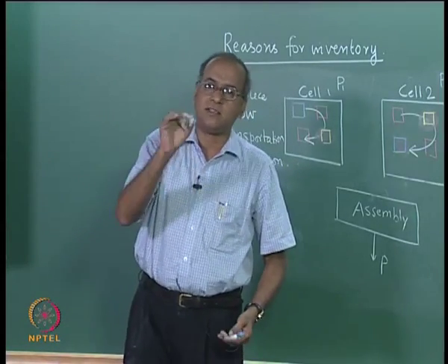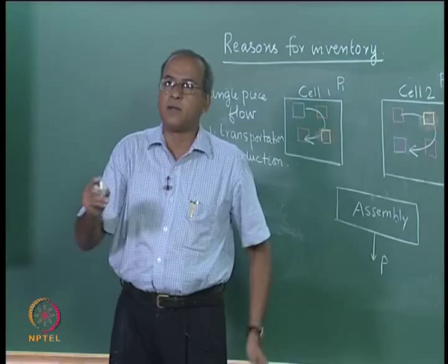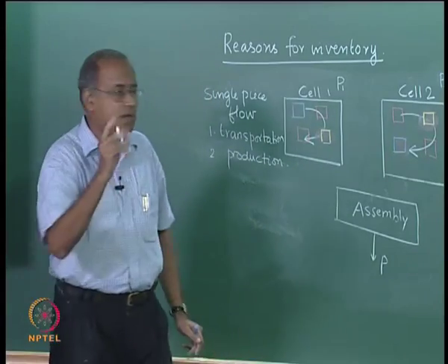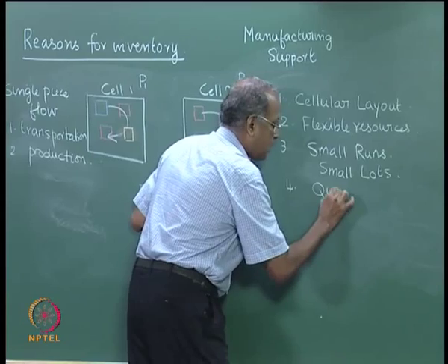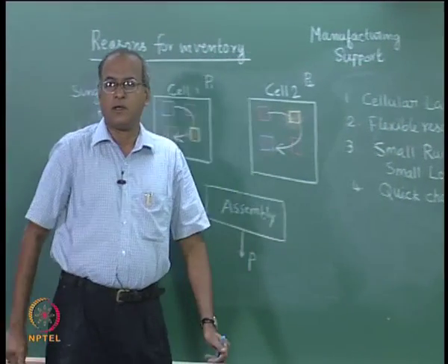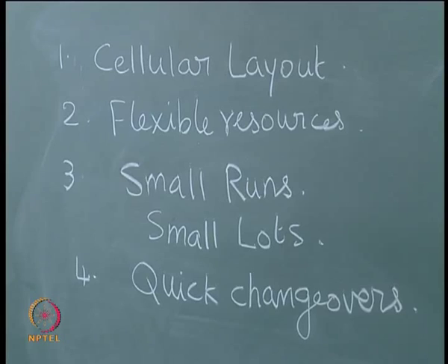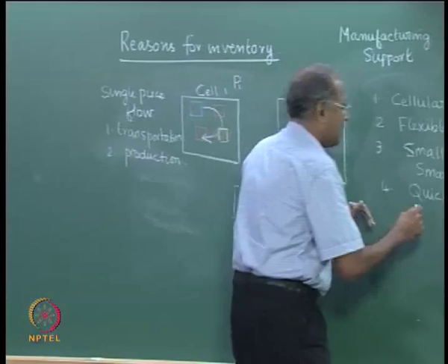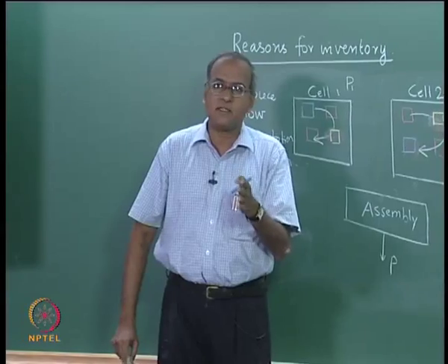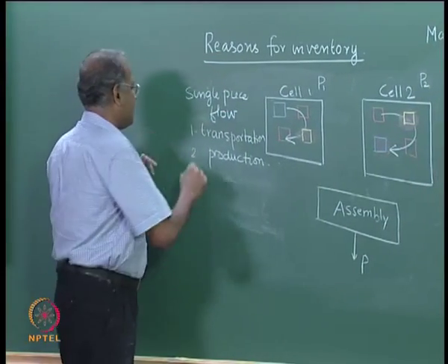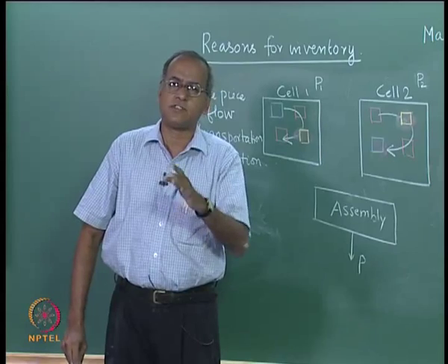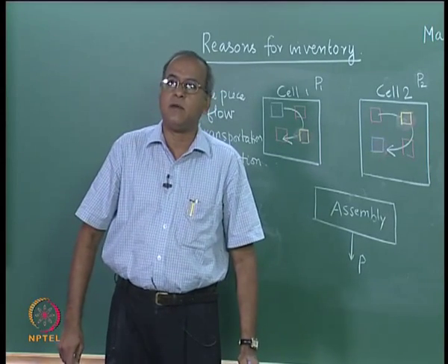So, when the number of changeovers increases, the time taken to produce also increases. If we do not want that time taken to produce to increase considerably, it is necessary to have a smaller time for setups. So, we move to what is called quick setups or quick changeovers. Every system that implements just in time will concentrate on reducing changeovers or changeover times. By reducing changeover times, we will be able to achieve single piece production flow, and single piece production flow is a necessary thing to strive at if one is using just in time manufacturing system.